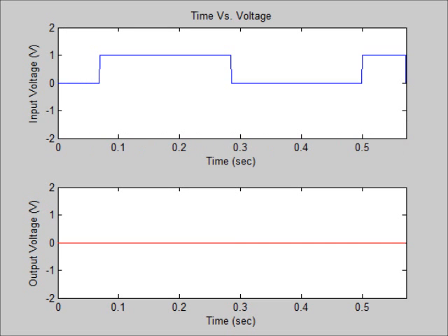So using a step function as an input, I wanted to show this idea of overdamping in an electrical system. So as you can see, the output voltage reaches the input voltage, which is the top voltage in blue, but it does so very slowly, and it also decreases very slowly, but you'll also notice that there's no resonance in the circuit.